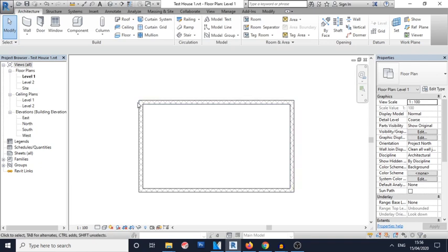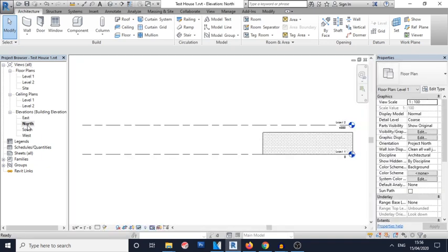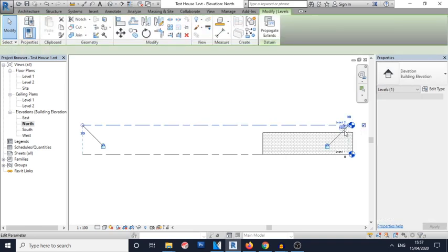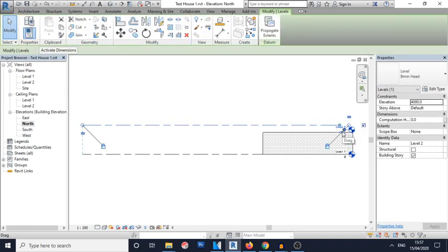And if you come to the left side, you see that in the views, you can switch elevation from a plan to the elevation. And then we have our 3-meter wall. There's a level above it at 4 meters. But I want that level to be the same as the wall. So I'm just going to click that level. And I'm just going to click the 4, excuse me.